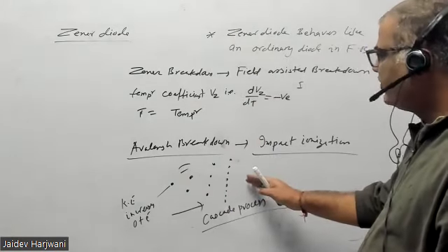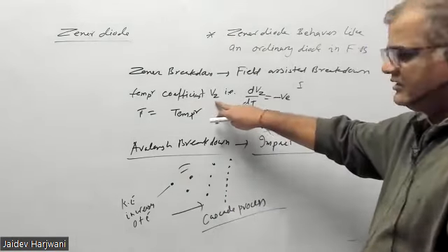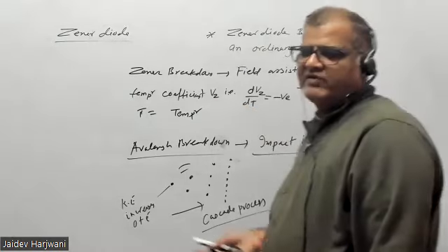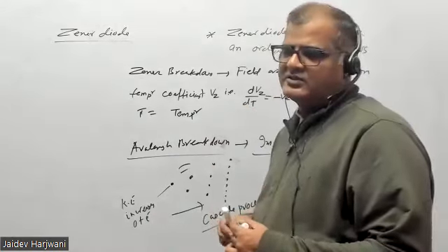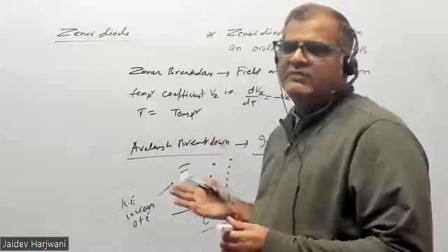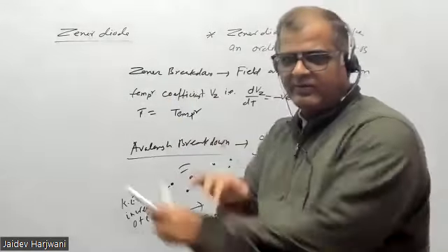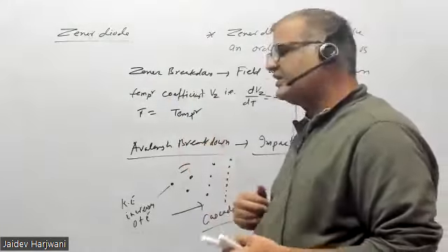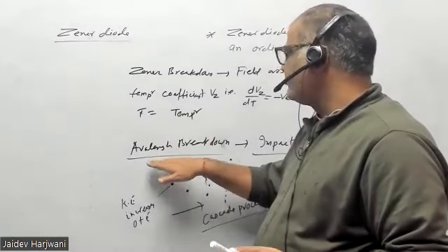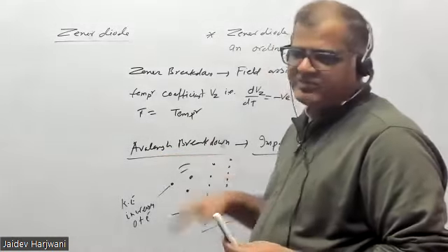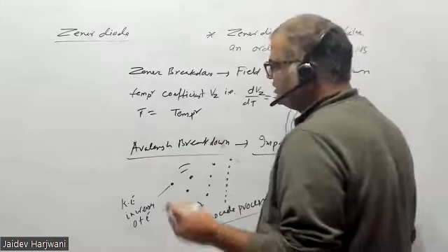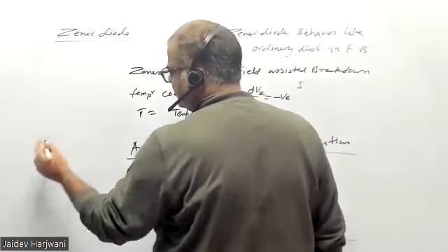So this voltage is generally higher than the Zener voltage. Zener breakdown happens generally at lower voltage. Suppose the Zener voltage happens at 5, the avalanche breakdown of the PN junction may happen at 7. Like this, the difference is there. And now the temperature coefficient of avalanche breakdown.